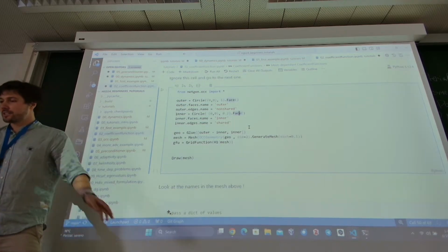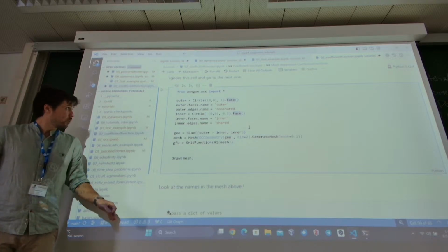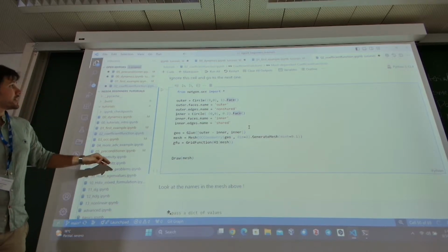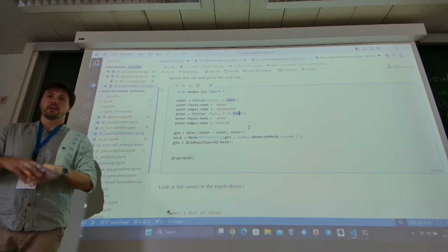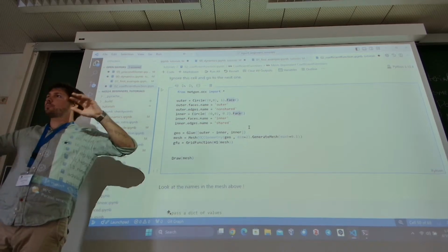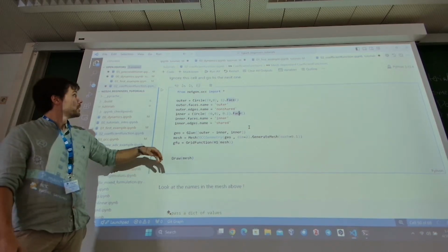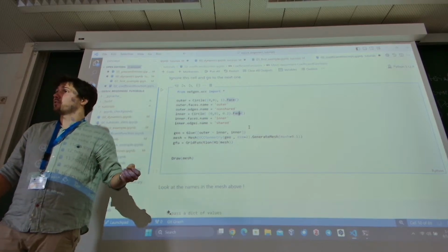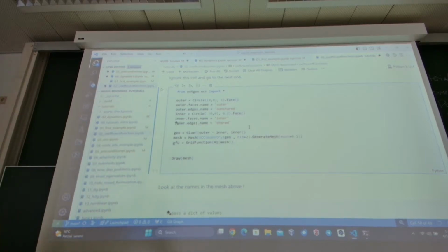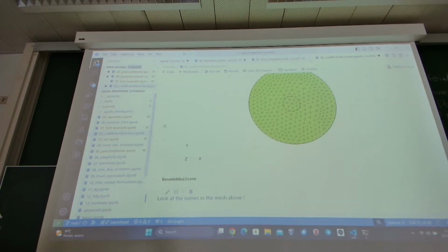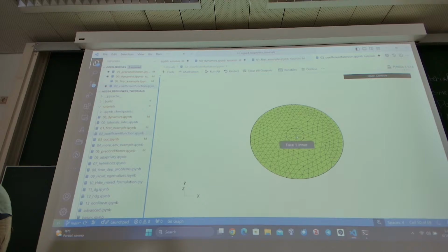So far, all the basics of the coefficient functions are done. One thing that you could be interested in is when you model a certain domain and you have some prescribed potential or a prescribed flux on the whole domain or on the boundaries, you can use some mesh dependent coefficient functions. So for now, let me just create a geometry. We gave some names to the geometry: this is inner, this is called outer, this is called shared, and this is non-shared, just four random names.